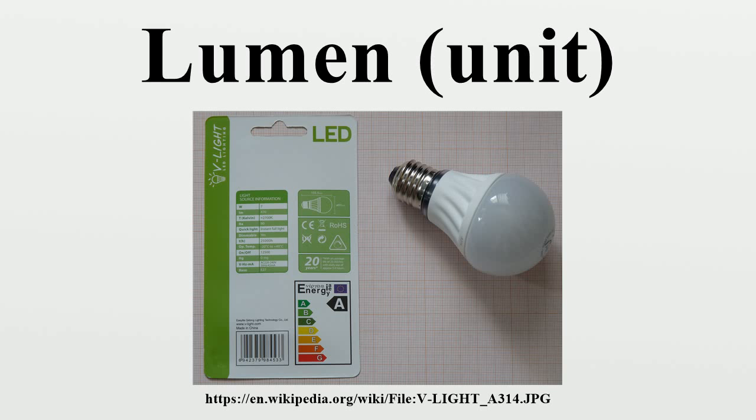The light output is then measured on a full white field at 9 specific locations around the screen and averaged. This average is then multiplied by the screen area to give the brightness of the projector in ANSI lumens.